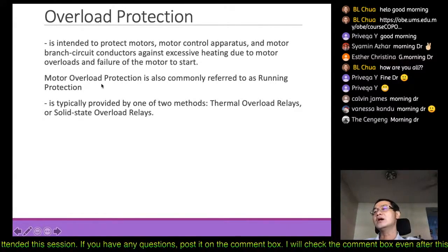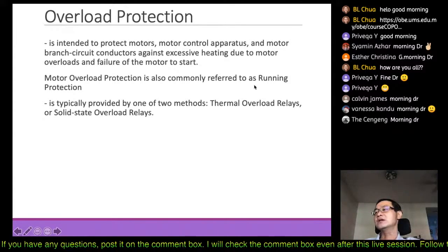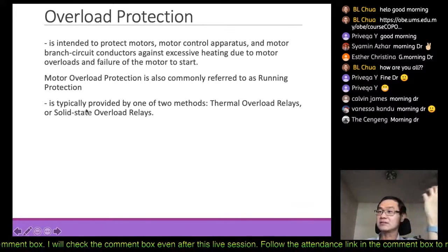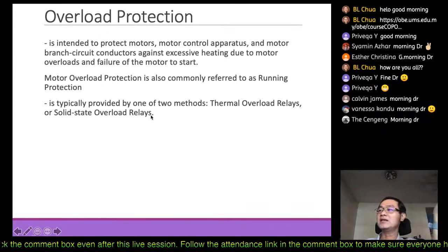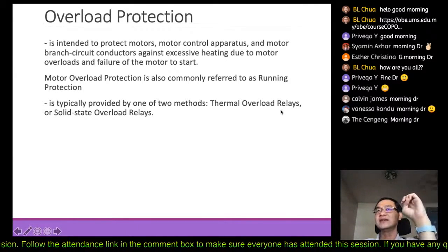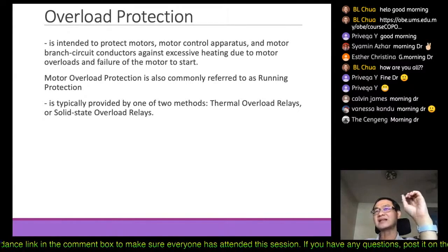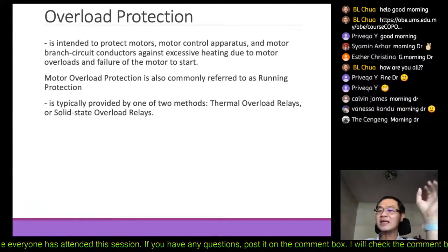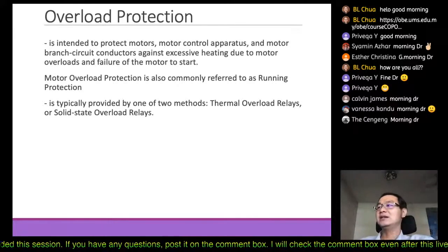And this motor overload protection is also referred to as running protection. Typically there are two ways: the solid state overload relay, or the thermal overload relay, which is not exactly detecting the temperature, but the way it operates relates to the temperature.